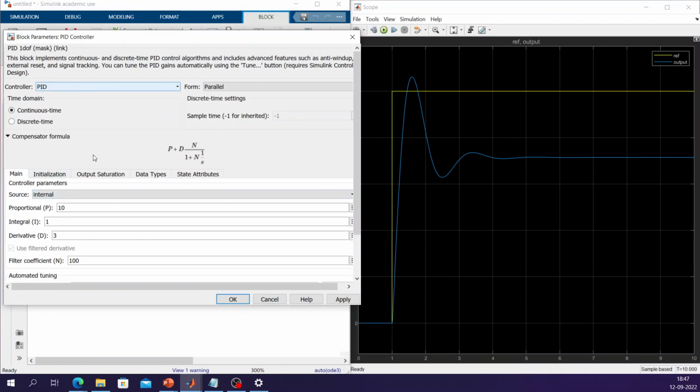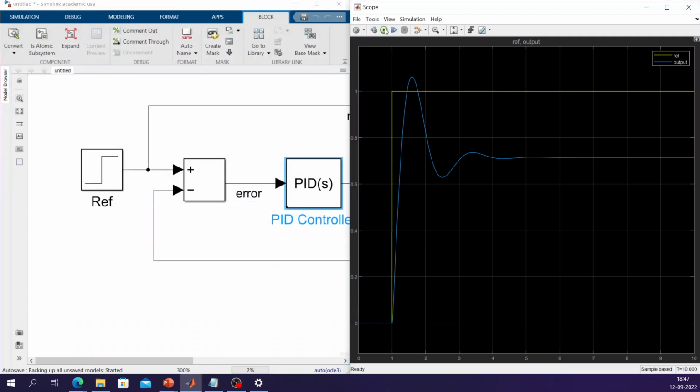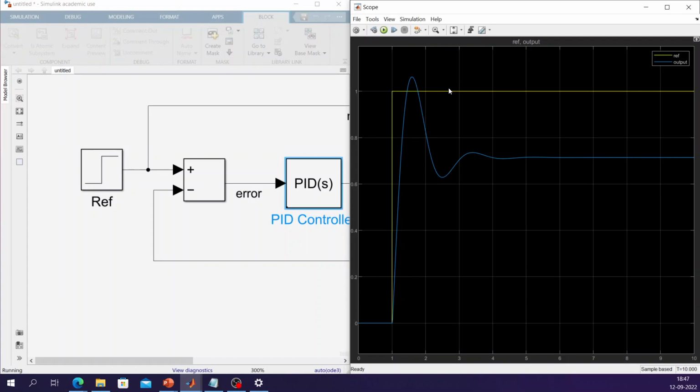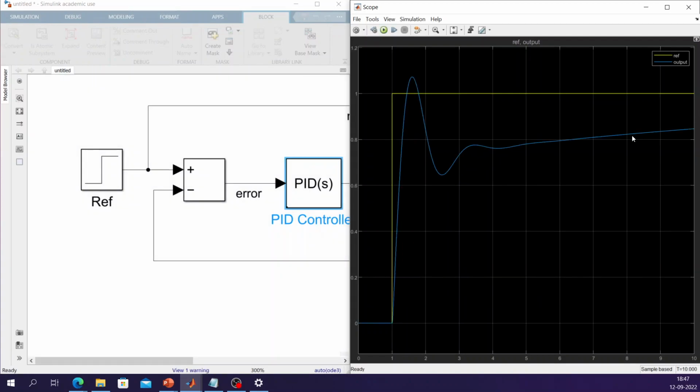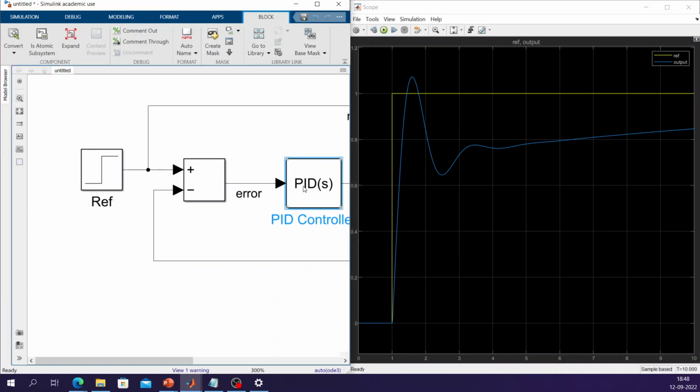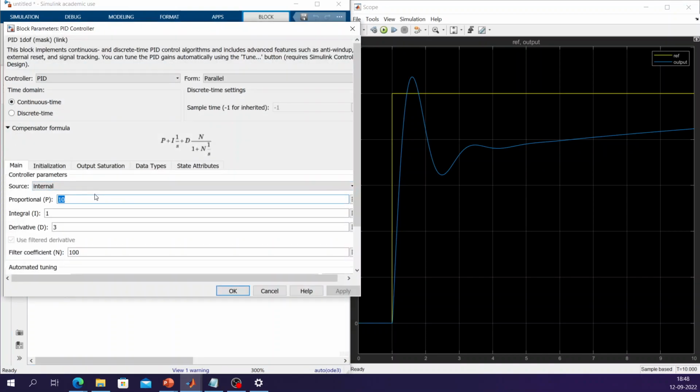and make it a PID controller, when we include the integral controller part, it ensures that we get zero steady state error. So once the system settles down, as we can see, it's approaching towards 1. Since our simulation is ending, we are not able to see that. So let us improve our gains again.